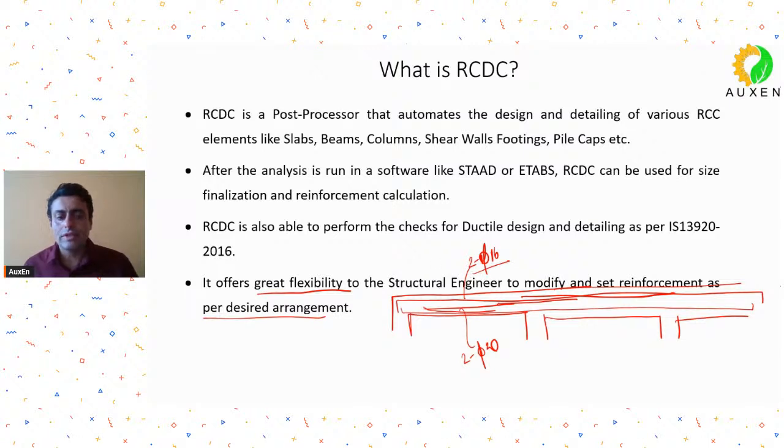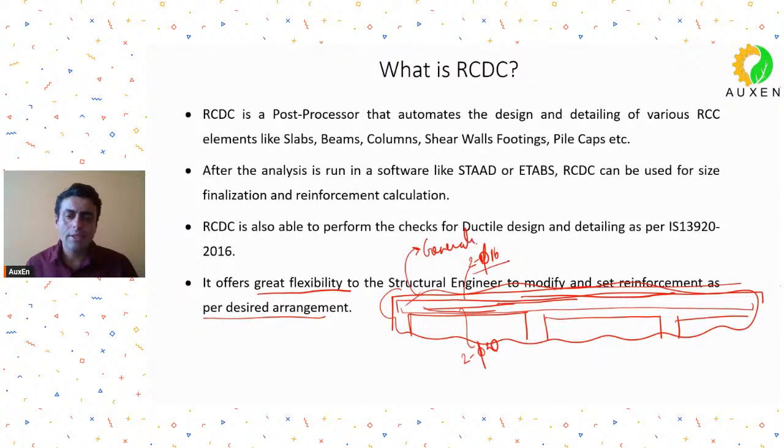What is the advantage of setting your own reinforcement as per your own desired arrangement? Once you are able to set your own reinforcement, then you can generate your drawings based on that. That is the big advantage, that you can generate drawings on the basis of the reinforcement arrangement that you have set. In fact, it will also check the reinforcement arrangement that you wish to provide.